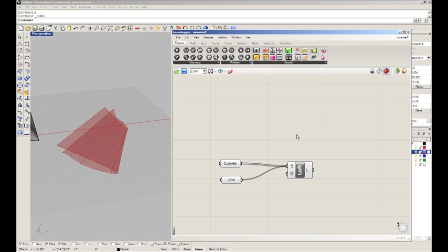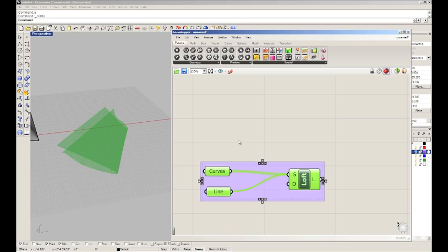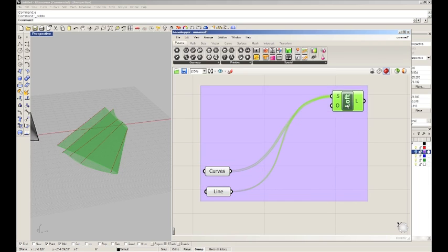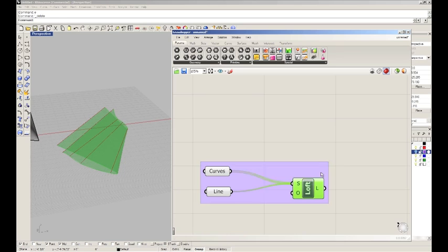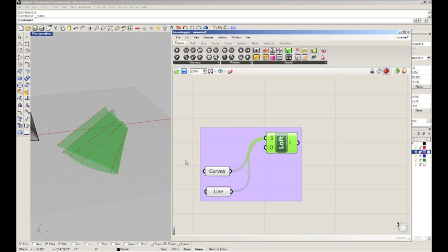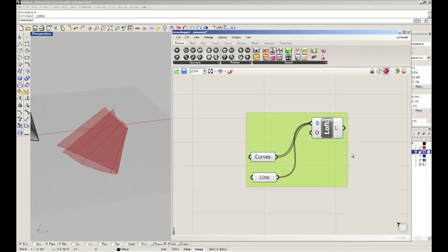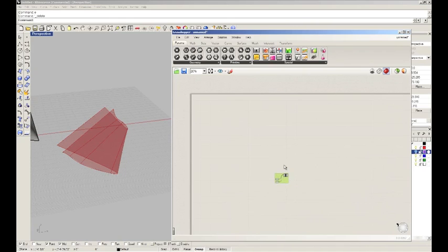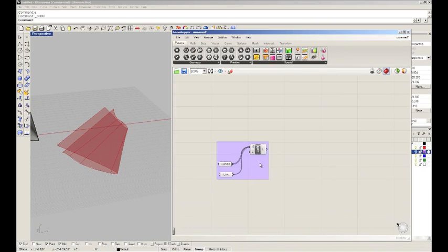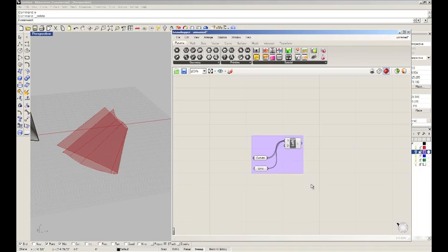One last thing in here is that if you select multiple objects, and this is going to be part of something that I'm designing and I want it to always stay together, I can press Control G, and it will group these things together. If I grab one of them and move it around, that purple box that indicates the group is going to move with it. These guys are always going to stay within this box. I can grab the purple and move them around together as a group, which is nice, especially when you start getting into more complex things.